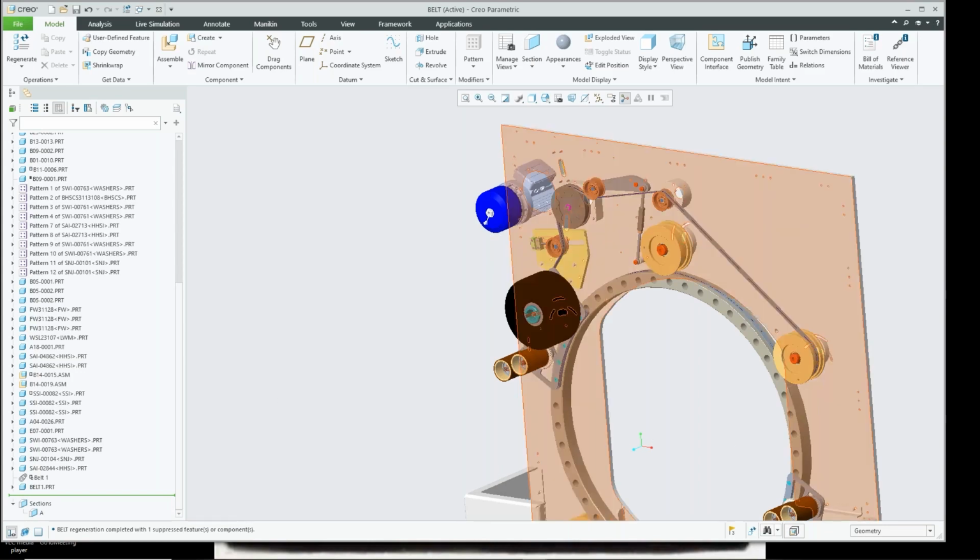So there's two statements, sorry, one's a question and one's a statement. When we were talking about the slider constraints, it says you are able to use datums on the fly. Yeah, definitely. Anything that we're creating, when we're doing any type of assembling, whether we're talking connections or regular constraints, on the very right end of our assembly toolbar, we have the ability to go and create any datums that we need for that assembly process. So yes, we can always create them whenever we need them, whether it be an axis, a plane, or anything like that to allow us to use in our geometry.